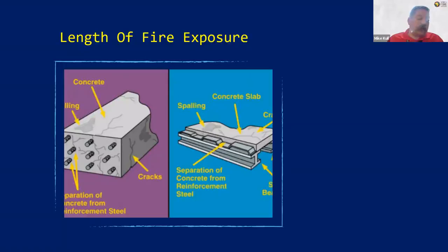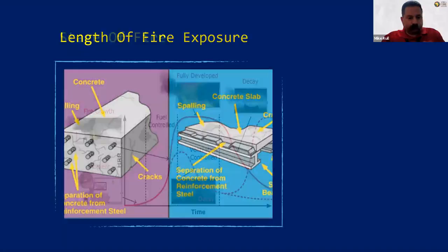As those beams expand, they may cause the concrete that surrounds them to crack, or you get spalling, where the concrete starts to crack and come apart because of the exposure to heat and flames. So the longer that fire's been burning, this is common sense, right? The longer the building components have been exposed to fire, the greater the potential we may have for some type of structural collapse.